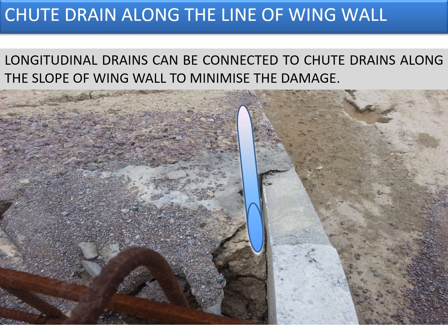the soil. So once the soil is eroded along the line of the wing walls, if you allow traffic on top of the road, then the vertical load will displace the soil below the road in the horizontal direction, thereby creating a cavity between the bottom of the approach slab and the top of the soil.